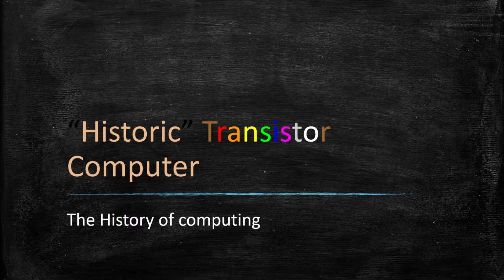Today we'll start building a historic style computer made exclusively from discrete components. While our computer will functionally be closer to a more modern 8-bit computer with a 16-bit address bus, so that we can actually do something with it, the technology employed will mimic the ones used in 1959's IBM 1401. It'll be diode transistor logic, commonly known as DTL.